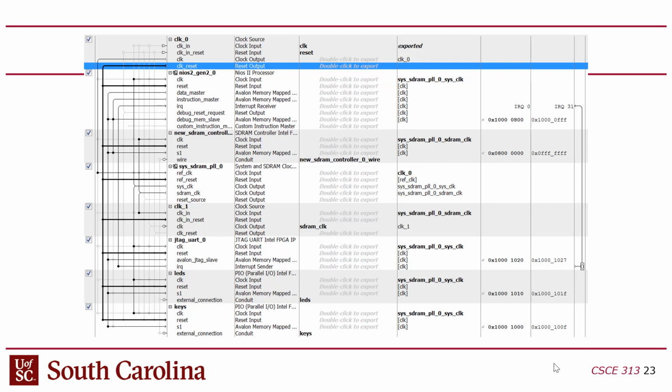Right. So this SDRAM clock, I couldn't remember if this is how we did it. The SDRAM clock, the out-of-phase 50 megahertz clock, connects to only two things. One is the external pin, so it can go out to the chips. And the other is the actual internal connection for this SDRAM controller that powers the SDRAM controller. Okay? Everywhere else, you just use the system clock.